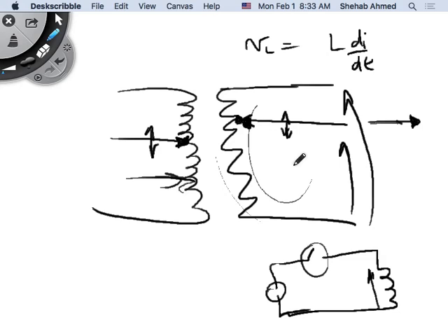So this is one of the problems. The way we would do it physically is we would make before break. So let's say I want to change from position 1 to position 2. I would maybe put a short circuit first around these two positions, right? I won't disconnect. I put a short circuit. I would live with a lower voltage or a higher voltage to my load for a while. And then I make first, and then I connect here, and then I remove this, right? That way I made before I broke. It's called make before break, right?